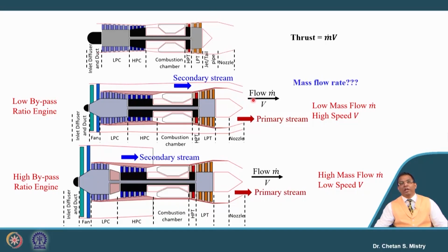Here this hot gas will be exhausted from this nozzle. When it comes in contact with the atmosphere, in a turbojet engine, because of the shearing action we will have a lot of noise generated. Now, in this case, the exhaust gas coming out, the hot gas, will be surrounded by the cold air, and that helps in suppressing the noise.